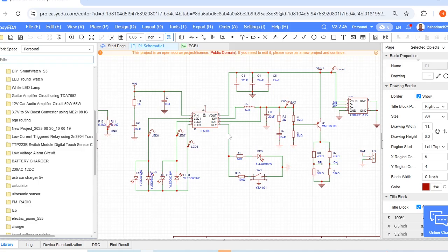If the component placement is bad, even the routing is bad, even if you don't know anything you did, you are increasing the noise. You have to pay attention to component placement.